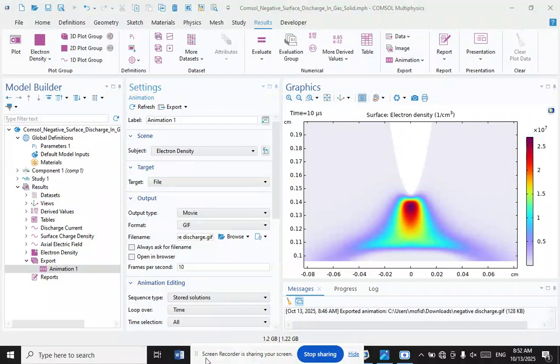The next one is humidity. Higher humidity accelerates the formation of discharge and increases the pulse current. It can also lead to a shift in surface charge distribution from a ring-like to a spot-like pattern due to the accumulation of more surface charge.